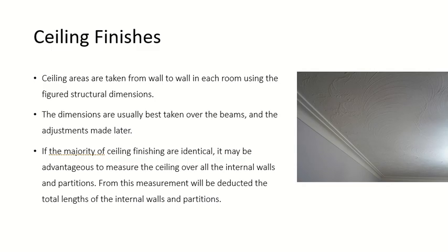This is what they are saying about the finishing, but you can keep this rule in mind: if I take the total area, I have to make just one deduction. This will be easier than taking one area for each room. It will have too many rows and too much calculation. So just keep this guideline in your mind.